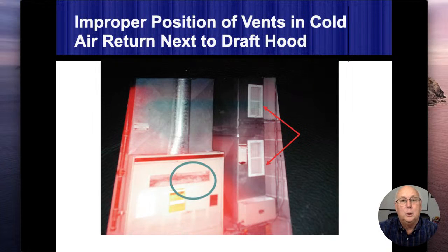So if we look at the drawings on here, and this was an actual home, it was taken a long time ago, natural draft furnace. What's a common solution if you make the ductwork too small and you're restricting the airflow coming back to the rooms? And when I mean ductwork, I'm talking about the return ductwork.